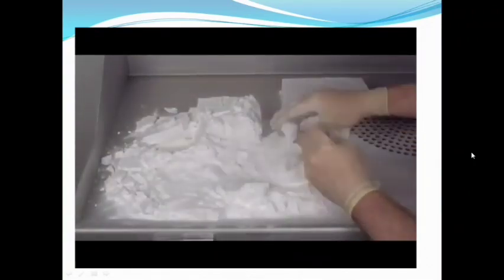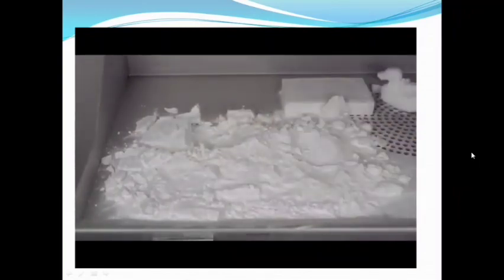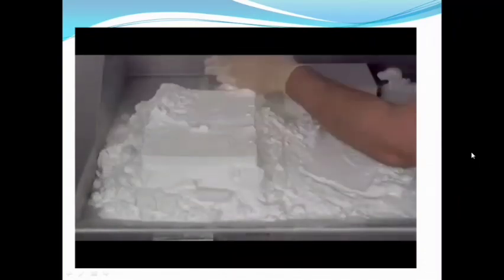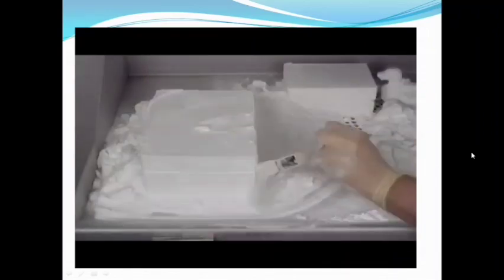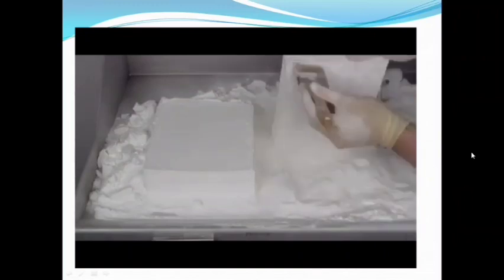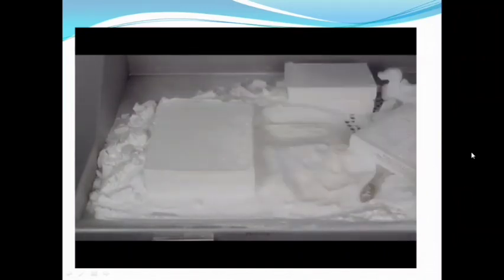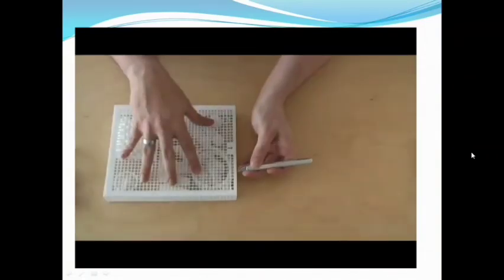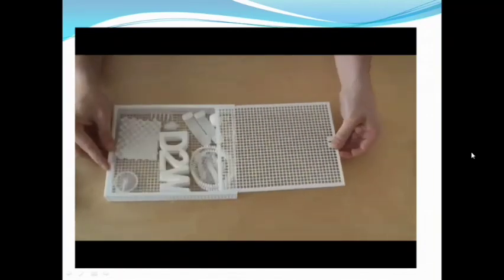After the completion of this, we come to post processing. The part is left in the cooling process in the machine before it is removed. It is very simple to engage in this post processing. We just remove the excess powders. That's it. After the removal of the powders by using the jet machine process, the finished component is taken out.